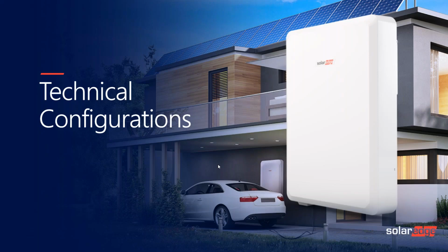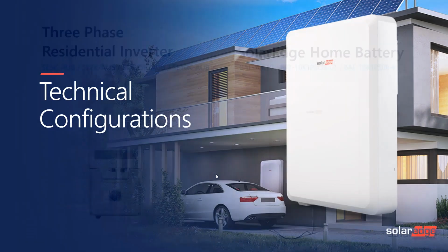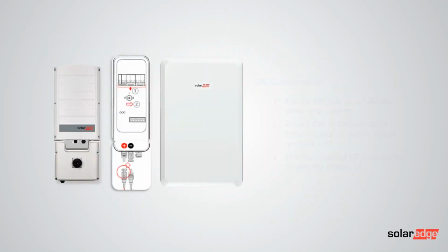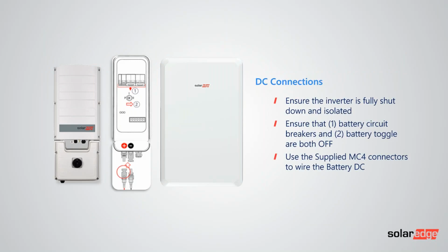So yes, I'm going to run through with you some of the technical configurations. Now, the first one, as Doug mentioned, is the integration between our three-phase residential inverter, that's the SC5K-AUB through to the 10, and the SolarEdge home battery. So when we integrate them, the first thing, it's kind of teaching you to suck eggs really, but make sure everything's turned off. And also make sure to use the supplied MC4 connectors to wire the DC coming from the battery.